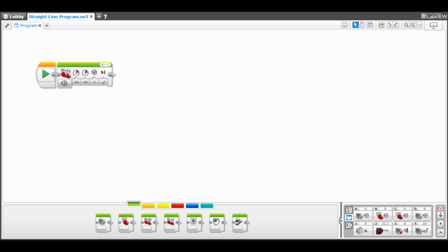The next control is the right motor control. It has the same properties as left motor control. Since our port selection is B plus C, the right motor is the C motor. The next control is rotations control. This is responsible for how many rotations the motors will go before they stop. The distance is measured in rotations because First LEGO League motors have a rotating hub on them. This control is very important because without it, the robot wouldn't know when to stop moving on the field.